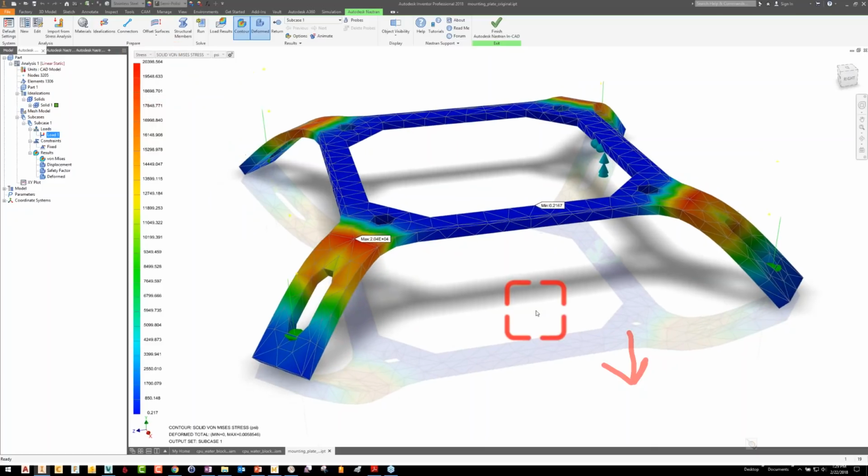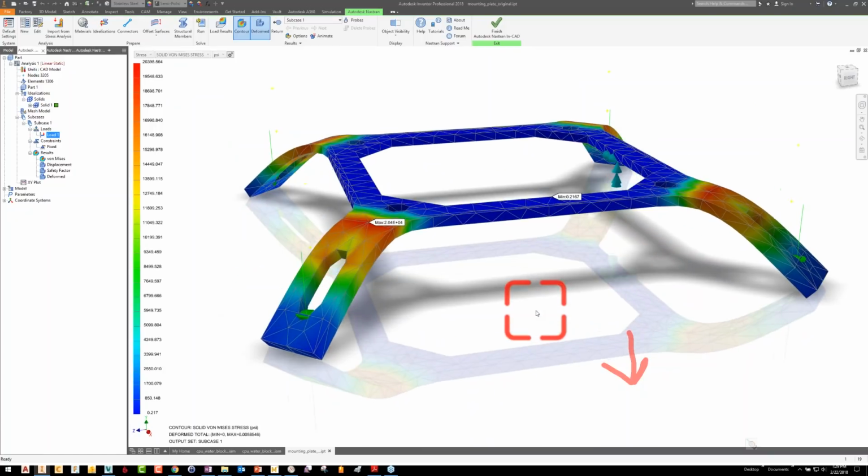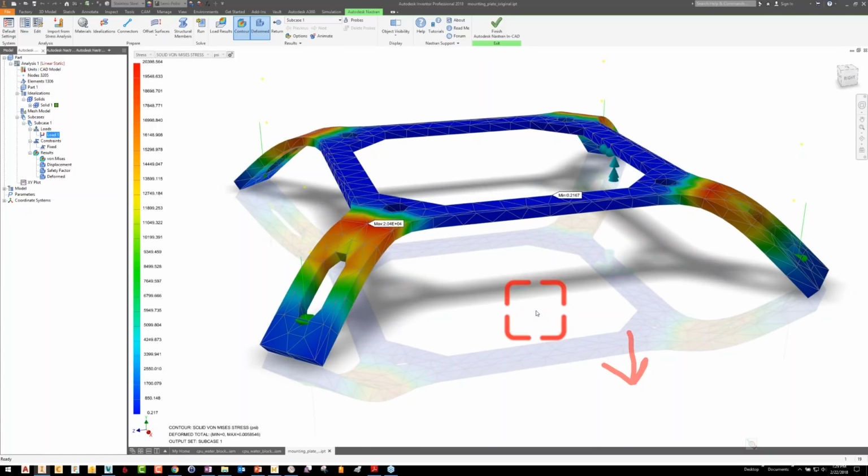It's also severely deformed, right? It looks worse than it is. Also very common in static stress is to exaggerate the deformation, because typically in static stress you're working with displacements that are small. In a part like this, which is about 4 inches across, you'd be expecting results in the thousandths of an inch. You start getting up over that into tenths of an inch, you might be exceeding the kind of displacements you'd be comfortable with in a static problem of this scale.